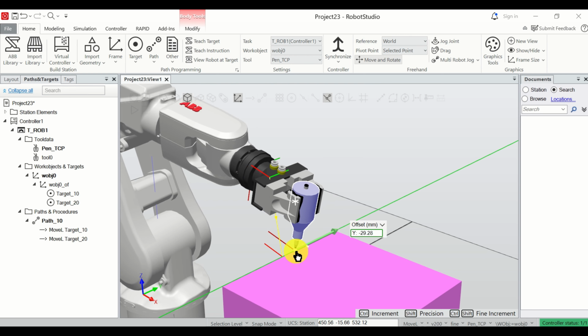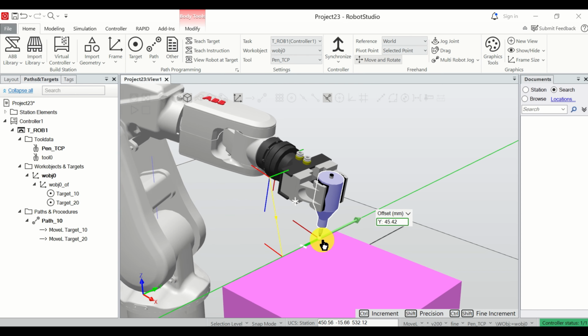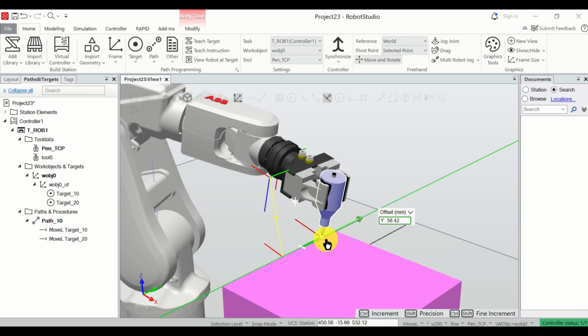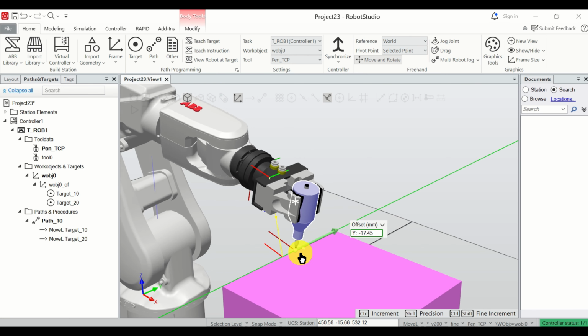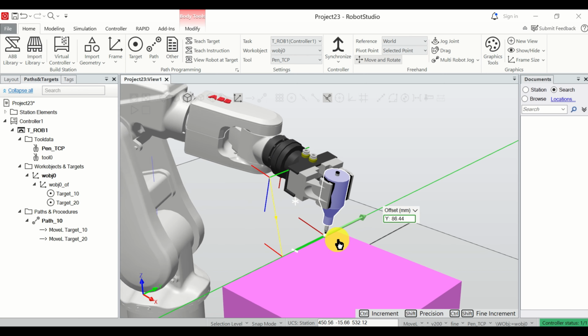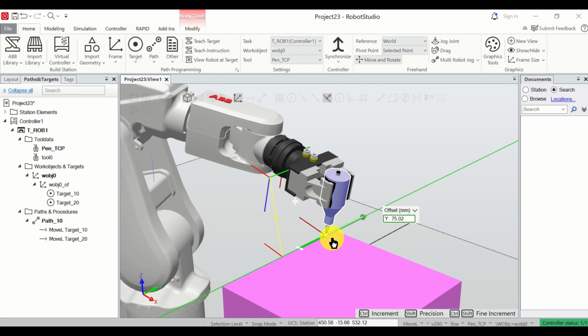So what's the issue with this? The issue with this is that this rotation might hit a singular point where you will not be able to move the robot due to the problem with inverse kinematics. Now, this is a very important thing, since if you memorize some point over here and if the robot twists itself, that is if the joints are in some weird position, you will not be able to move the robot. So it's always a good idea to manually later on adjust the position of these joints, and I will explain you how to do it later on.